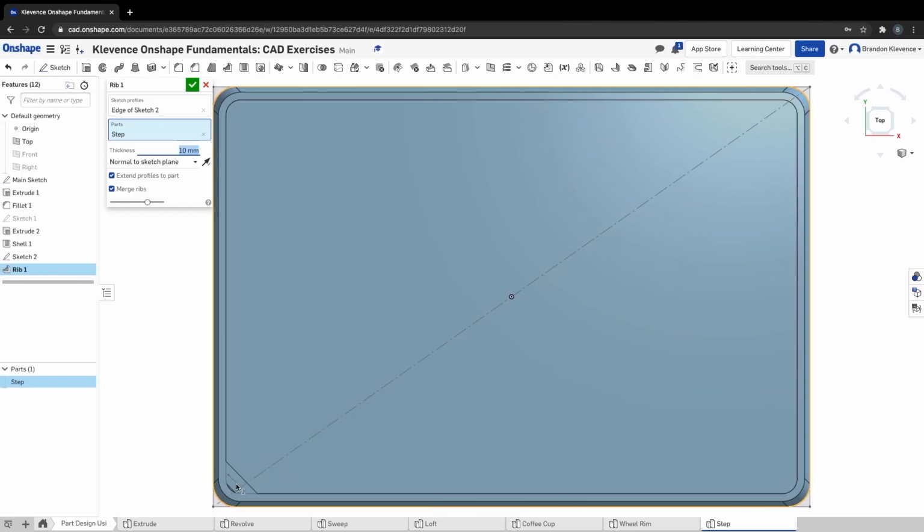Again, rib is like you're starting to create some sort of texture or extended part. Ribs are really good for structure within parts as well. So in this case, it's maybe like the ribbing is good for having it grip your shoes, but also it's adding structure with minimal material.